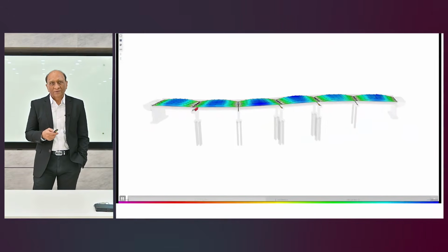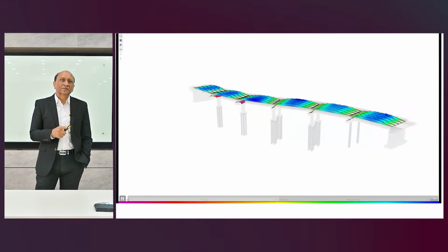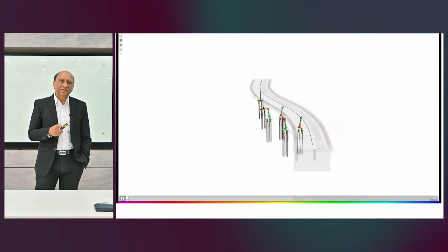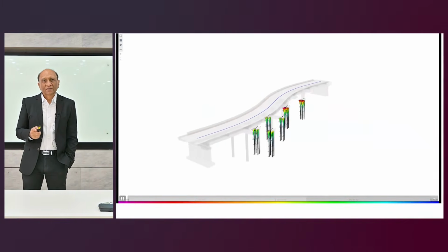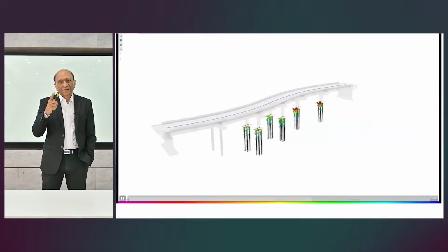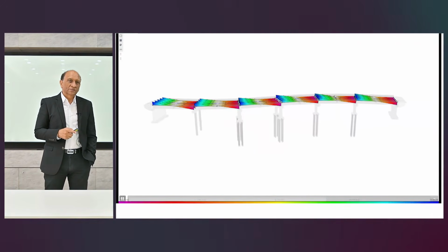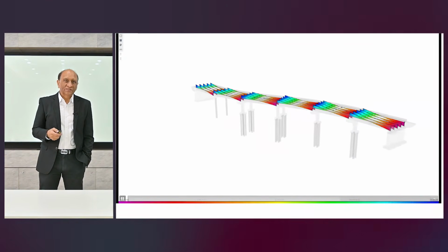Notice here that these shell analyses are automatically converted to beam forces or moments by using the section cut concept, where the integration of the stresses is done to get those forces everywhere. Whatever model we use, we ultimately get back the bending moments and shear forces that we need to do the code design checks.